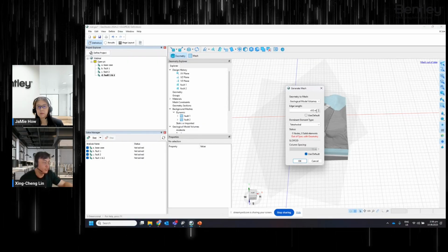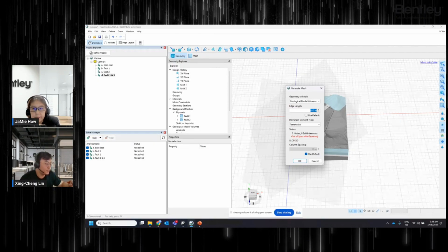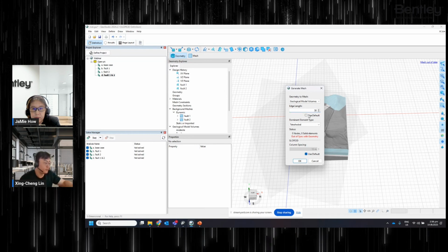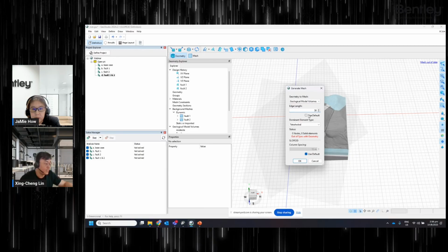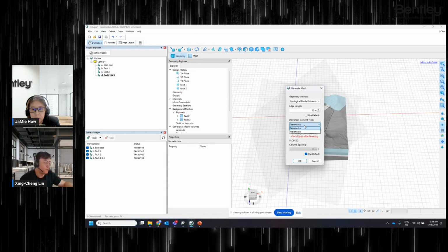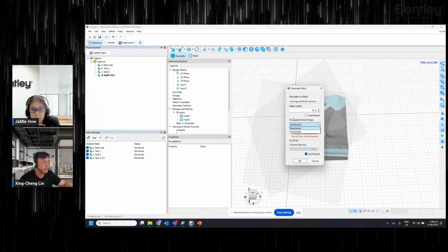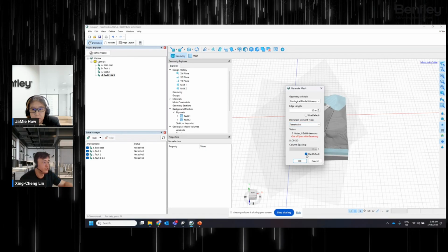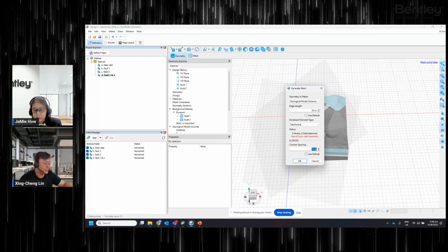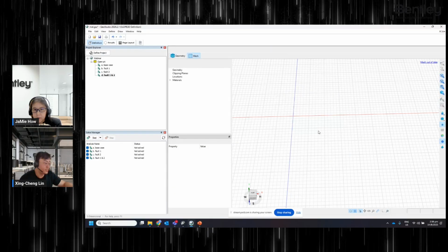Now we see that the current mesh is very coarse, because the parameter defined is quite large. In this case, I will change it to some lower values for better mesh refinement. And down at the bottom of this dialog is the Slope 3D column mesh settings. We have the option to generate tetrahedral or hexahedral elements. In this case, we go for tetrahedral. I'm going to tune down the column spacing from default to 5 meters, and hit the button to generate.